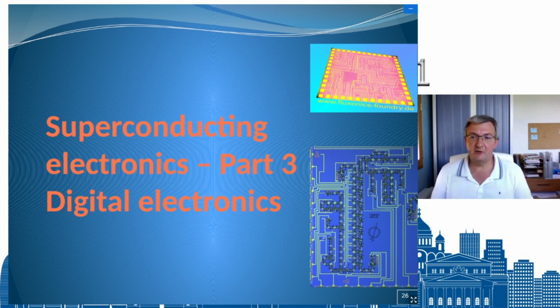In fact, we use spiral coils because you can have, for the same area on the chip, an inductance which is not exactly equal to the number of turns, but nearly, right? So it's basically about the same as a solenoid, just the geometry is slightly different, so you need to calculate it specifically. But that's the reason why we do that.